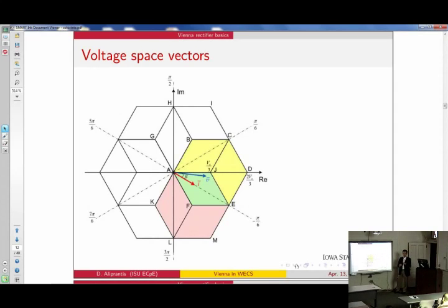So you have 3 switches, and each one can give you, let's say, 3 different voltages. So 3 times 3 times 3 gives you how many? 27. Actually, this inverter can give you 25, but I don't want to go into that detail. But all these points are put here. So from an inverter, you get discrete points, depending on how you switch the switches on and off. By averaging the discrete voltage that comes out of the 3 switches in time, you can get any voltage inside this hexagon. So, for example, if you want a voltage to be inside this,